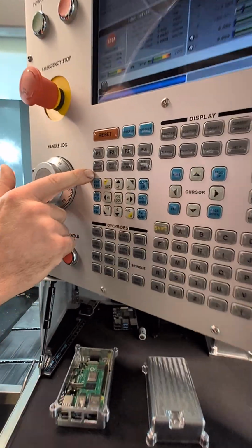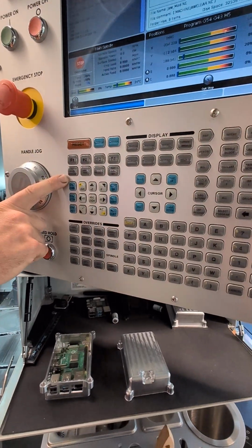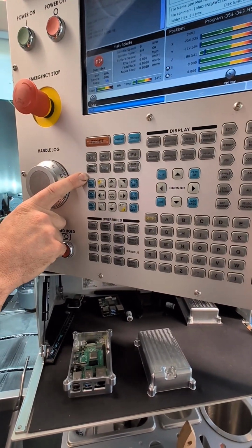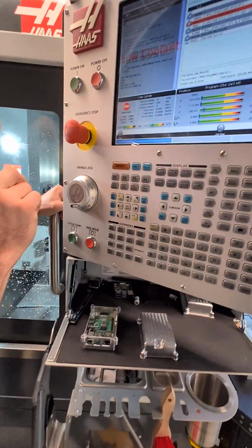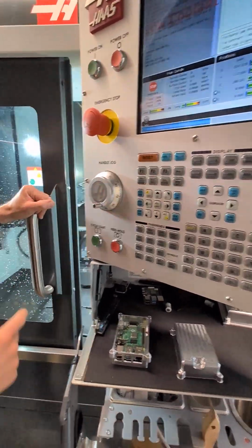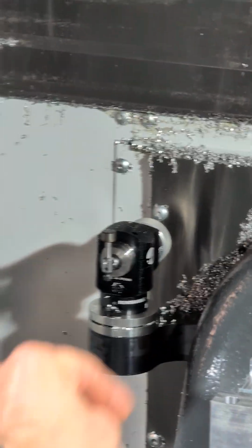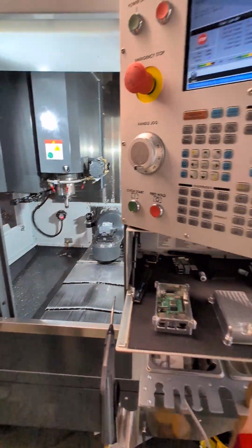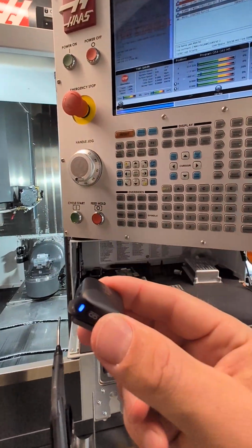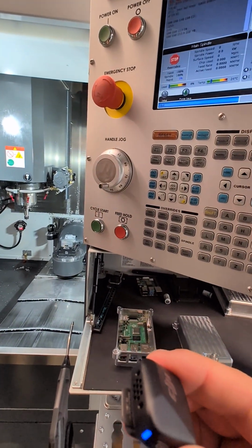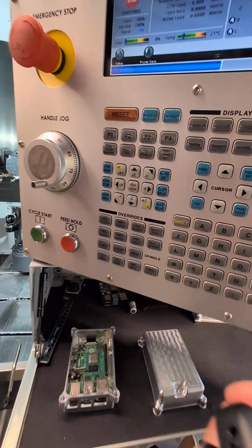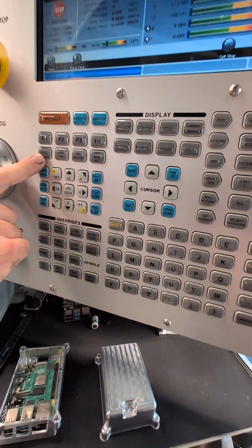This button here, tool offset measure, it's used to set tool offsets. Now, because you have the Renishaw probe, well, the tool setting probe is the OTS here. Yep. That's that one. So the machine will bring that under the tool, and it'll come down and touch the tool. We'll run through that. Yep. But that will set tool offsets.